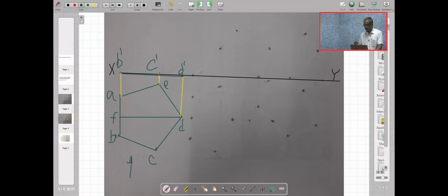Now I am tilting so that the lamina is making an angle of 45 degrees to HP. So this is my stage 1. In my stage 2, I am tilting my front view at an angle of 45 degrees. I am taking the same length here and the length is inclined at an angle of 45 degrees. Now this is my new front view. Let me also name these points. Let me call this B dash, C dash and D dash.